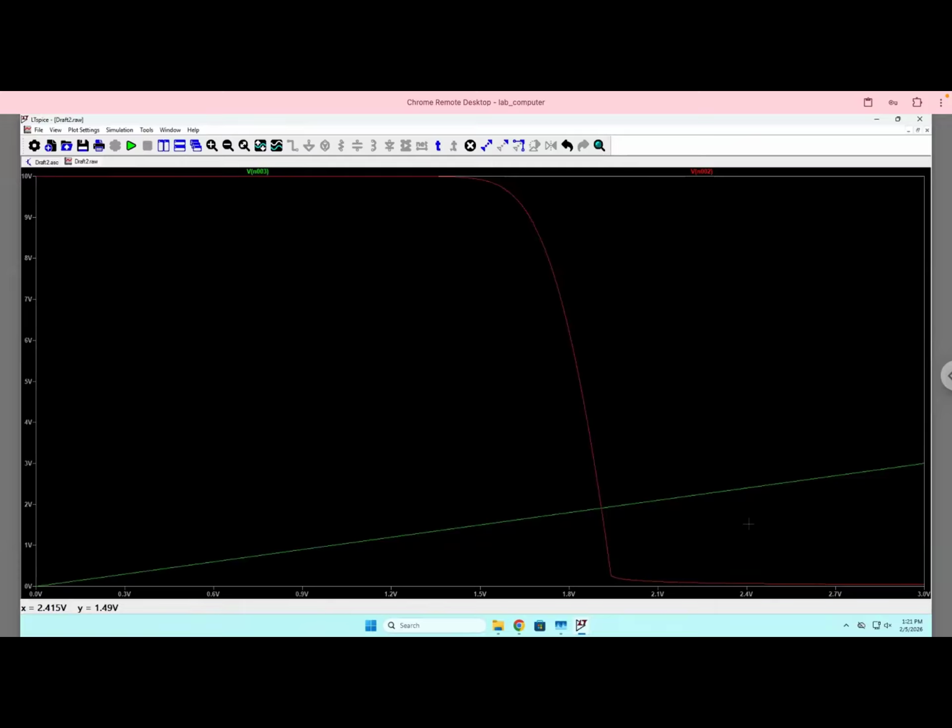So let's say 10. You just multiply the two, and then you can say that's your voltage gain, V over V. But if that response isn't linear, then you would say for this portion it would be 10, for this portion it would be 20, at this portion it would be 0.1. And you'd have to compensate for the lack of linearity with controls, which gets messy. Yeah. And you would have to have a digital system, and we're just trying to do something analog here.